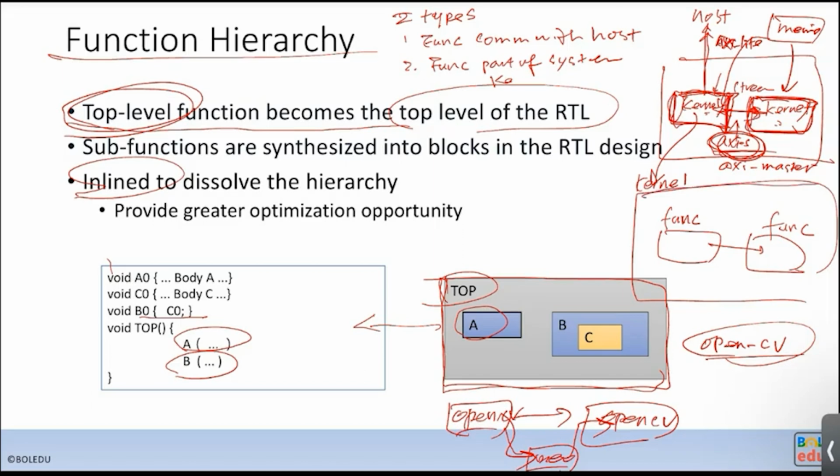Inside the kernel function, for each function interface you will use the HLS built-in interfaces like AP valid and AP acknowledge to transfer data. I will introduce that in later lectures. Those types of interface are not exposed as external interfaces, only among the functions.